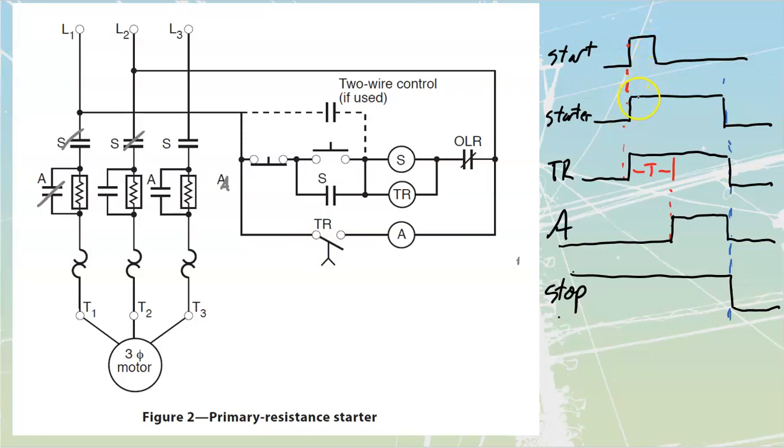So I'm going to have my motor that's going to be operating under acceleration right now, and then it's going to go in time, and then I'm going to see that at that point it's going to close the accelerating relays, and my motor is going to be operating at full speed. You might just call these things different names. If I were to introduce this, I would call this the startup, and I would call this the full speed. And it's going to make it easier to explain to anybody that's not electrically savvy.